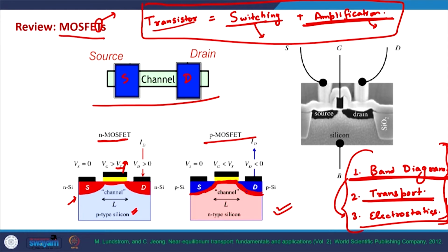When the gate voltage is larger than the threshold voltage, we will have a channel below the gate and this will switch on the device. So, by changing the gate voltage, we can switch the device on or off. That is the basic switching operation of these devices, and it is achieved by changing the voltage or the electric field on the gate terminal, the third terminal.